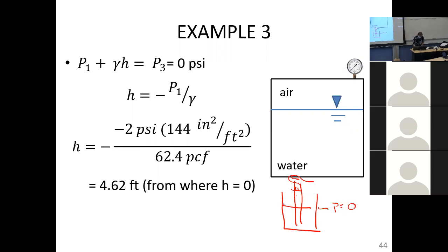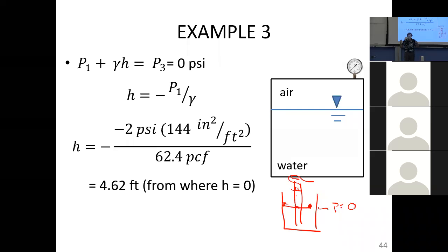And so if this is 0 along the free surface outside here, dP/dx is 0. If I move from this location to this location, I'm going horizontally, even though physically to stay in the continuum, I went down and up into the straw, but I went through a continuum. The pressure, dP/dx, has to be the same. There's no change in pressure if you move in x. Okay, so this would be the exact analysis of what's happening in the tank. And you've seen this before, I know it. You just never applied math to it.